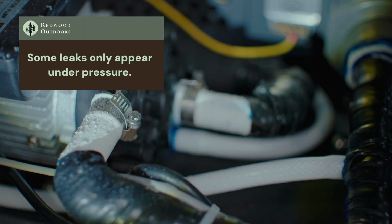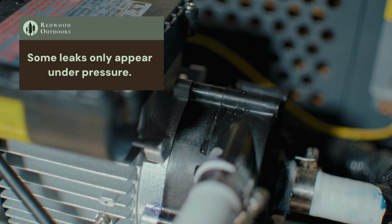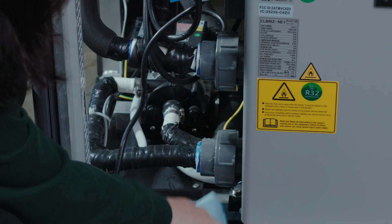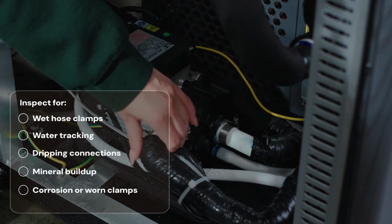If a leak is not immediately visible, observe the system both while powered off and while circulation is running. Using dry paper towels around fittings and hose connections can help identify slow drips that may otherwise be difficult to spot. Loose hose connection points are one of the most common causes of leaks.